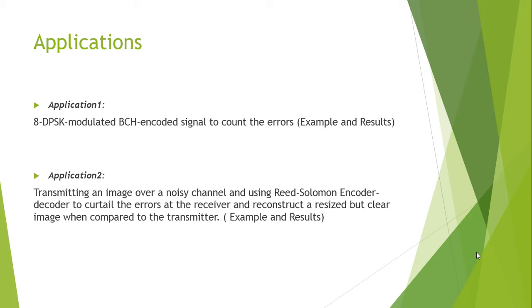Then for satellite and bandwidth communication systems, we know that bandwidth requirements are pretty stringent and percentage error introduced in the channel is also very high because of the enormous distance of propagation. So ECC schemes like Galois, Reed-Solomon, Turbo, LDPC, they find good use there also. So now let's talk about applications which we can illustrate and see through code.